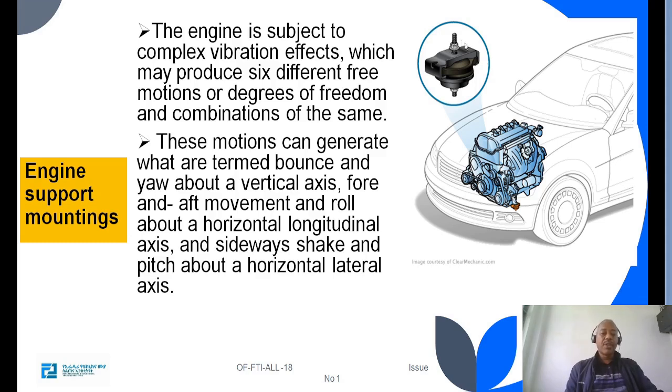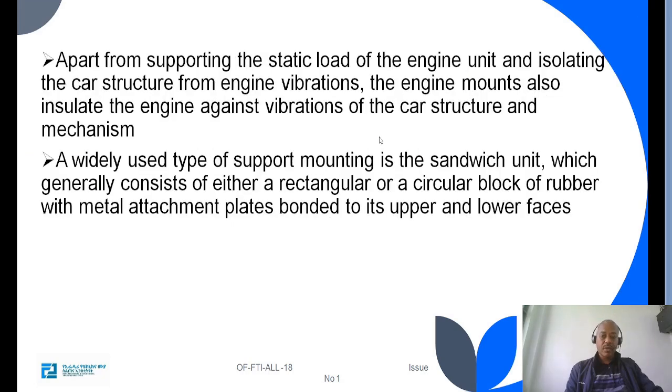This is the engine mount or support. Apart from supporting the static load of the engine unit and isolating the car structure from engine vibration, the engine mount also insulates the engine against vibration of the car structure and mechanism.